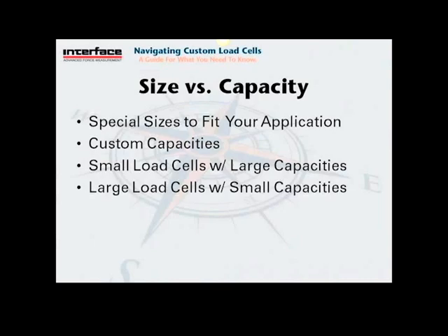As you get close to the limits of size and capacity, whether you have a small part with a high load or a large part with a small load, the performance generally starts to suffer. Strain gauges work best when the stress flow is parallel to the grid lines. So if the flexure doesn't have proper design considerations, then that may not happen and it induces more errors into your part. An example may be a 1210 10K flexure.